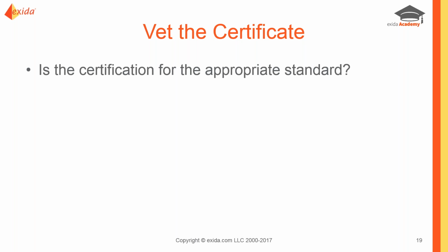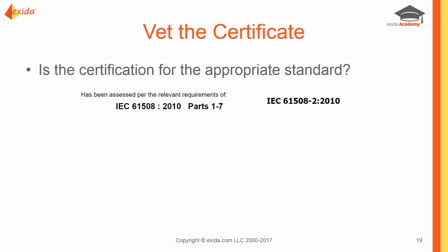If we're looking to certificates to say, okay, I'm just going to go certified components, let me go find out what's out there, we need to vet those certificates because there's a lot of documentation out in the general population that may not meet all of the criteria for SIL certified. So your plans and procedures need to have tools and techniques within them to help the users vet these certificates so that your designs end up being based on certificates that you know meet all of the requirements, or you understand what's missing from other documentation that might be presented, what needs to be augmented.